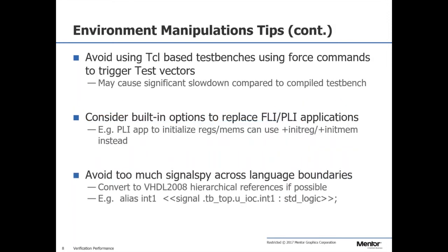Avoid using a Tcl-based test bench. Hopefully none of you are doing that. That's saying don't have a test bench that's a bunch of force commands in a Tcl file. Have it be a VHDL or a Verilog test bench that you're writing in the language. A Tcl-based test bench is going to be really slow. On the other end of the spectrum, if you're doing C programs, so you're hooking up C or something to your simulation test bench via the PLI or the FLI, there are built-in options that make sure that you can optimize. And if anybody is doing that, contact me and we can see if there's a better way for you to be doing that.